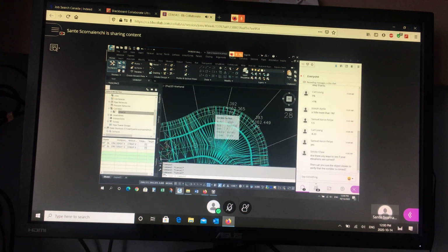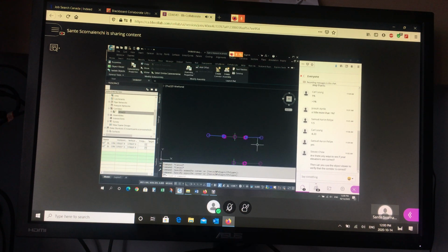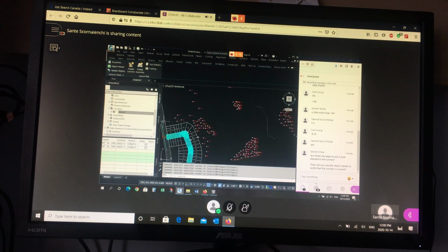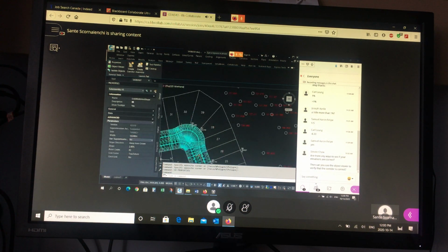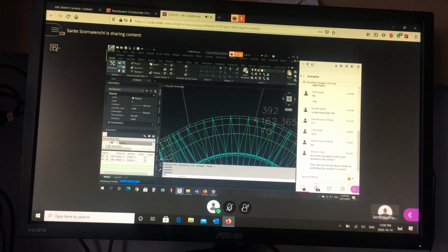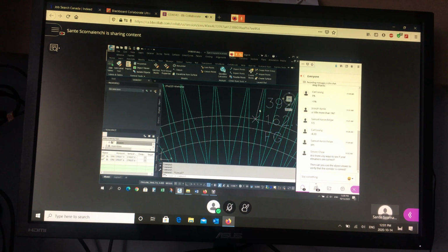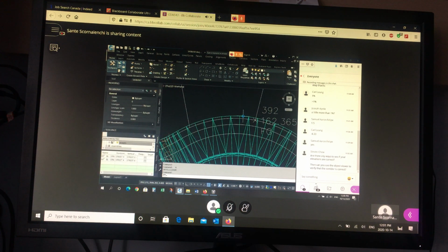Okay. How far beyond doesn't matter, right? But it can't be at the street line, it's got to be a little bit further in. So I made it 6 meters, you could make it 6.5, you could make it 7, you could make it 10, it doesn't matter. You're not going to go that far, right? I can make these boulevards, all the boulevards, 10 meters, right? If I make them 10 meters, when I rebuild the corridor, it gets a little bit fatter. But that doesn't change what the elevation would have been here. As long as it's past, you're going to get a number, and that's what you're interested in. Okay, so it doesn't have to be that wide, but wider than the actual. Never stop at the edge, go a little bit further.